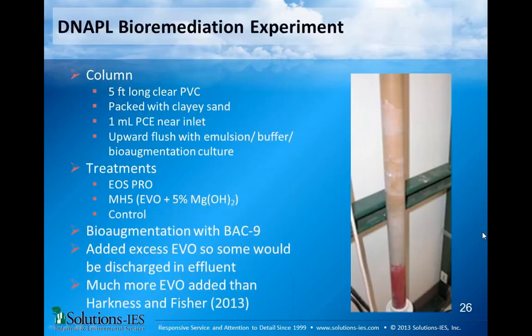If you can get to it, there's a lot of other very good competitive technologies that may be more appropriate for really, truly pooled DNAPL. Thermal, excavation. I'm not actually a real big fan of doing bio after ISCO just because of the changes, but some people do that. So for pooled DNAPL, yes, there are many probably superior alternatives.